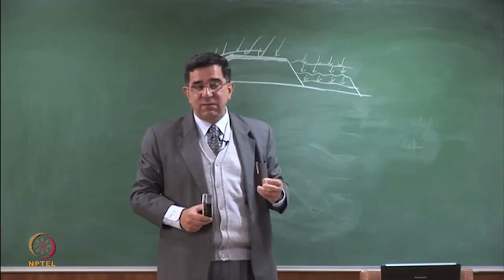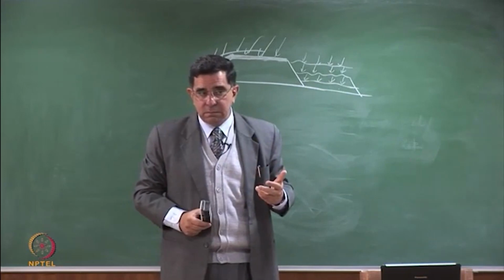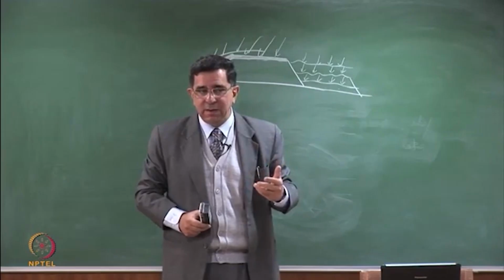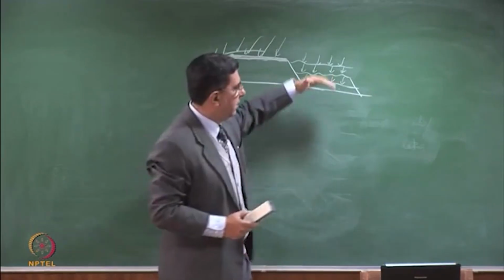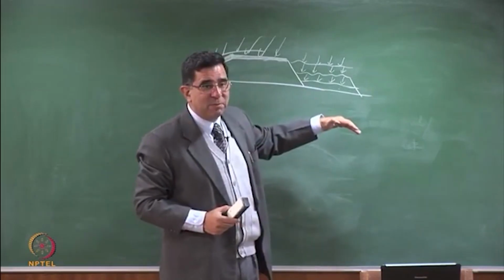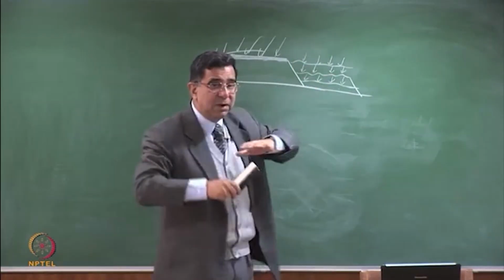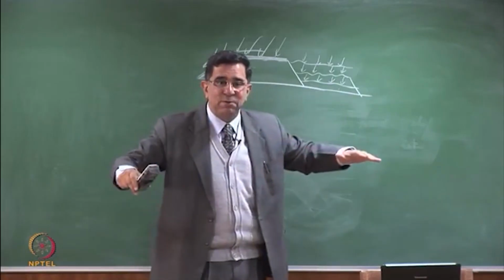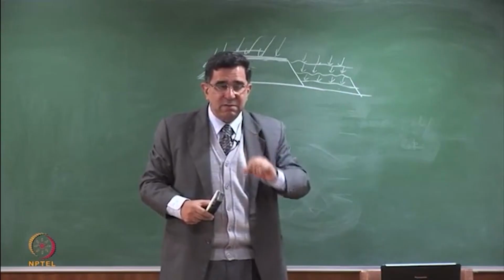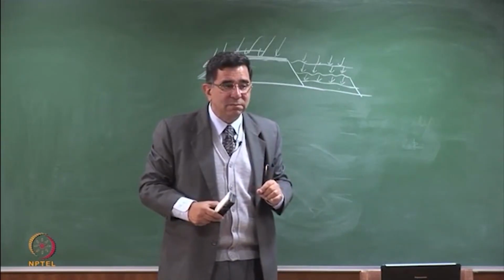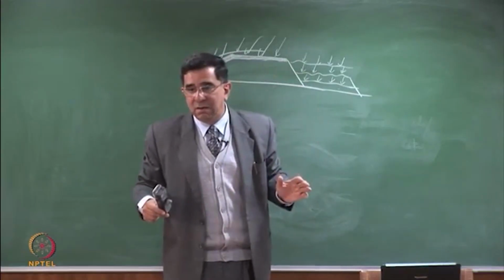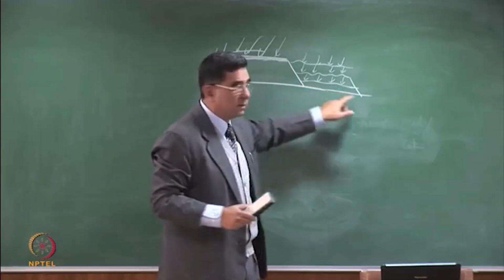Well, the waste itself has some absorbing capacity. Even if it doesn't have some absorbing capacity, it has some permeability. So what falls on the top takes some time to come down. If it takes some time to come down, the peak will be gradually spread over a period of time when the waste thickness is large. But when the waste thickness is small, then the time lapse between what is falling and coming to the pipe is very little. So actually this is the worst case.